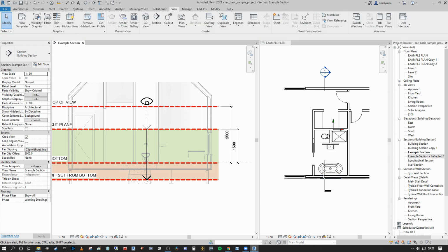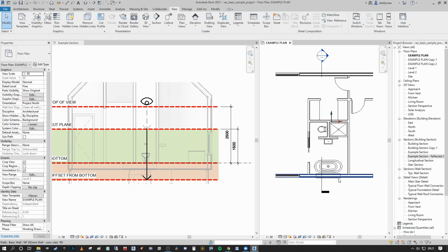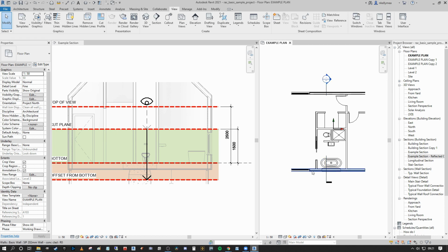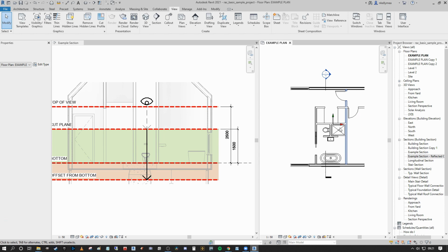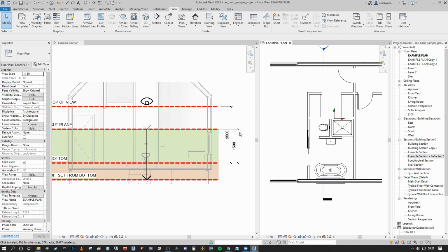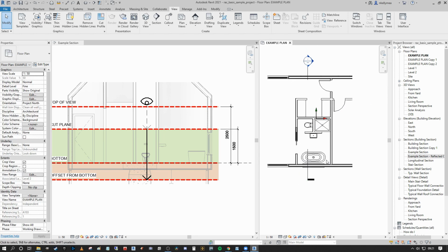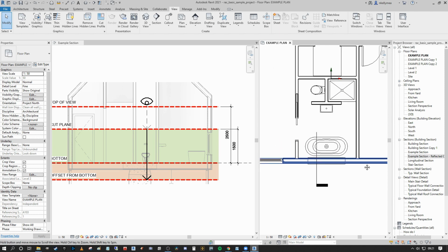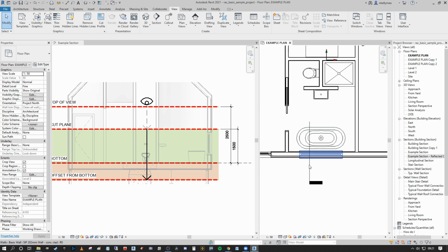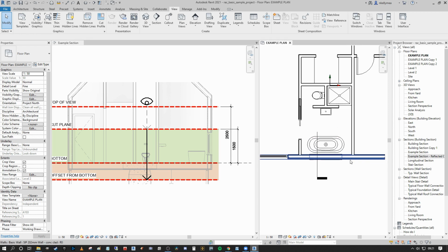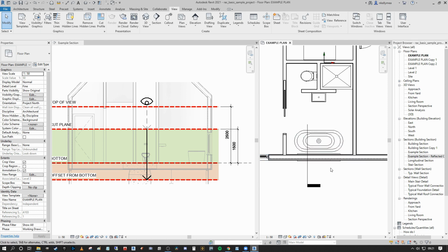As you can see, the presentation is not correct here now. We still want to see the window from the architectural perspective presented, but we also want to show our doors cut correctly and all the miscellaneous items cut at the 1500 level. So how do we show the window correctly cut in isolation if it's not crossing the cut plane? Because it doesn't intersect the cut plane, it's not showing as an intersected element anymore, and we want to show it as an intersected element so that the contractor can come along and actually place the window correctly and doesn't miss the window in this location.